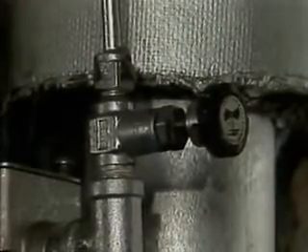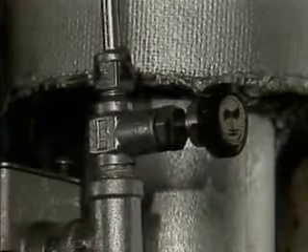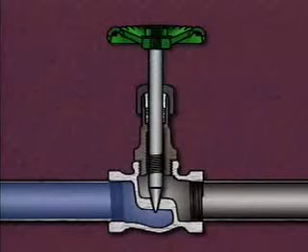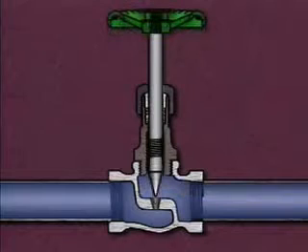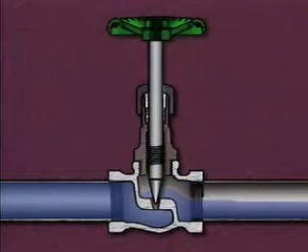Needle valves are generally smaller and longer in relation to their piping than other types of globe valves. As this cutaway illustration shows, a needle valve seat opening has a very narrow diameter. When the valve closes, the disc descends deep into the seating area. A small movement of the valve stem causes a small, gradual change in the flow rate through the valve, which makes the valve capable of precision throttling. So needle valves are often used when precise regulation of flow is needed.